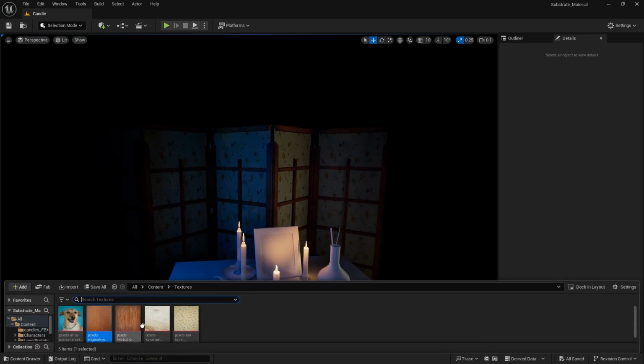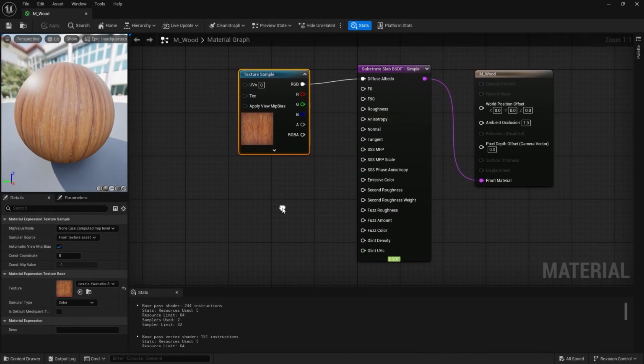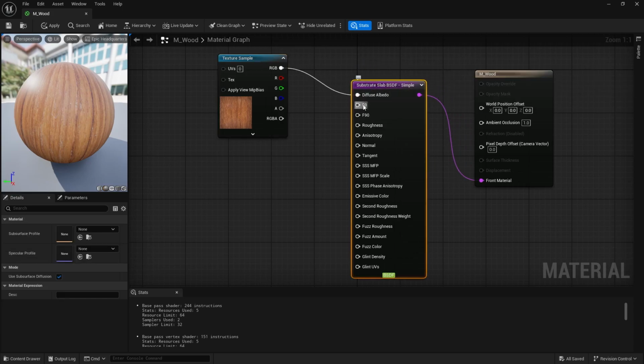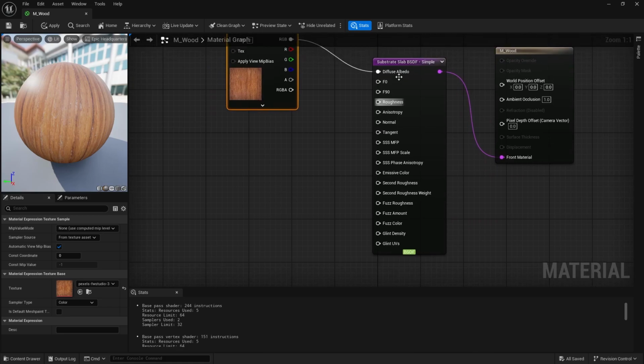Now I'm going to set the wood materials parameter in the materials folder, and here we are. Like I showed in the slideshow, F0 and F90 are the parameters we would like to look at now. F0 is basically the highlight that comes on a shader ball, or any geometry, from the front sides. F90 describes the light cast on the geometry at the end curvature areas.